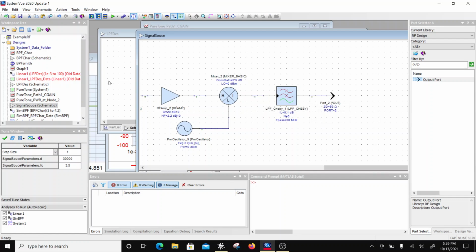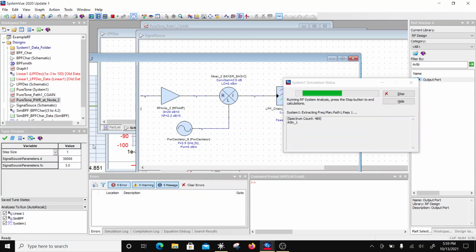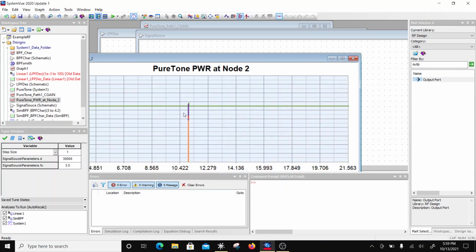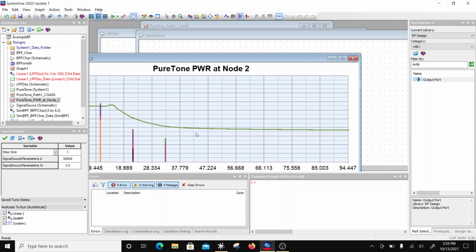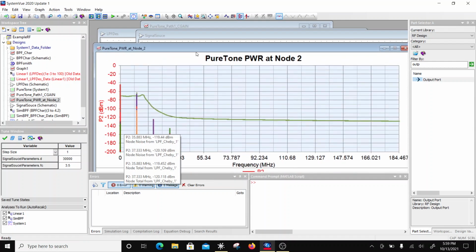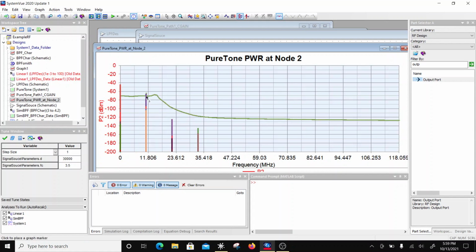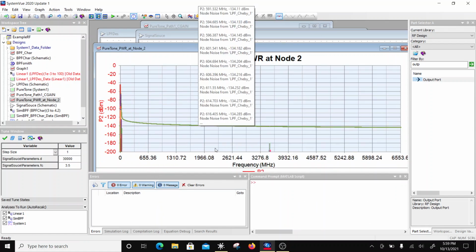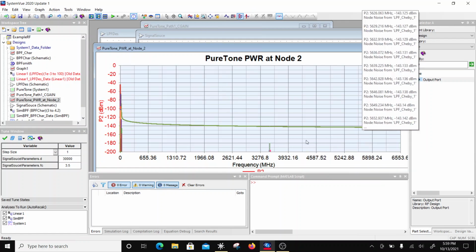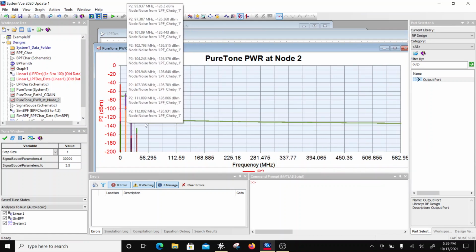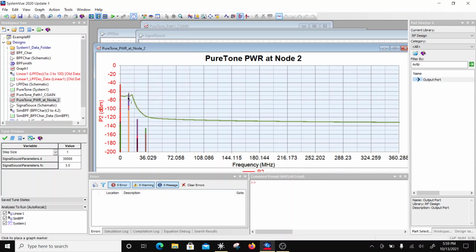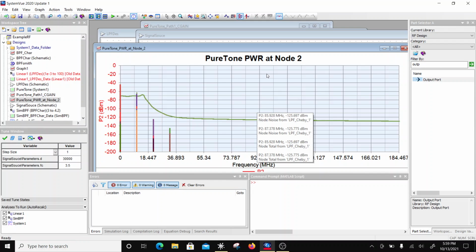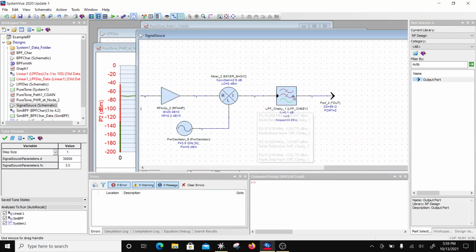And if I look at the characteristics, they are hardly going to change, because the LPF doesn't do anything. It's 0.1 dB. But it cuts out all other components. You can see that it cuts out all other components. So you are just having the baseband over here. The rest is all cut out, right? You can see all these high frequency components are gone. So our focus is on baseband here, and this is the edge of our baseband, 11 megahertz. Okay, so now I have given you some idea of how to construct this receive channel.